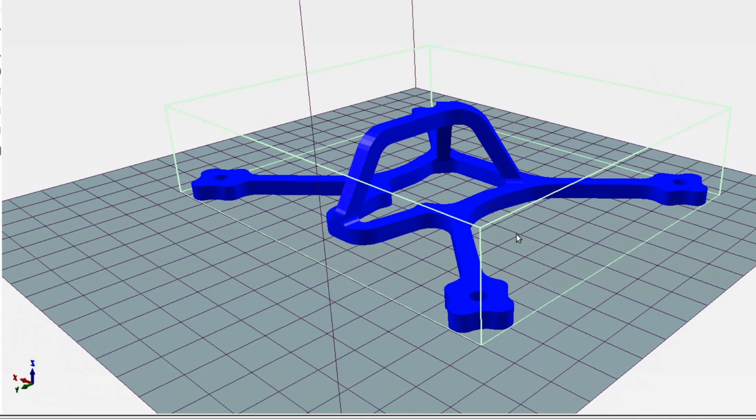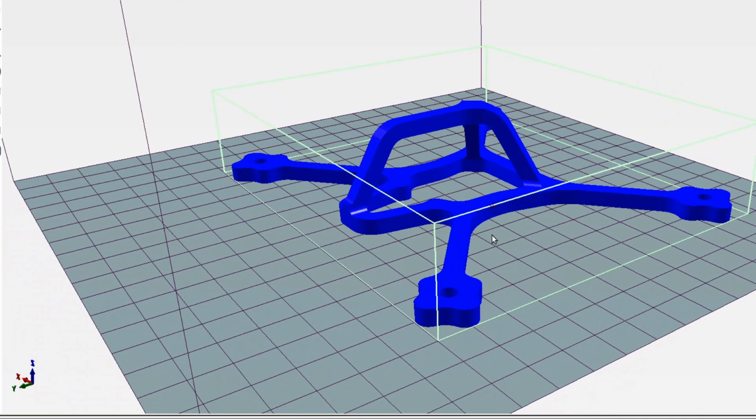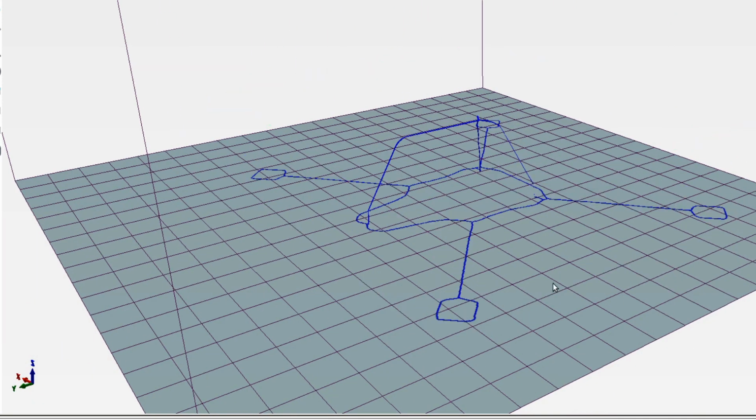Unlike in 3D printing, we don't need to generate the path for every volume of the object. We only need to ensure that the fiber is laid along the longitudinal direction, and the next parts of the process will be able to consolidate this material. And that will form our target object. So now, we need to transform this 3D object into this path.